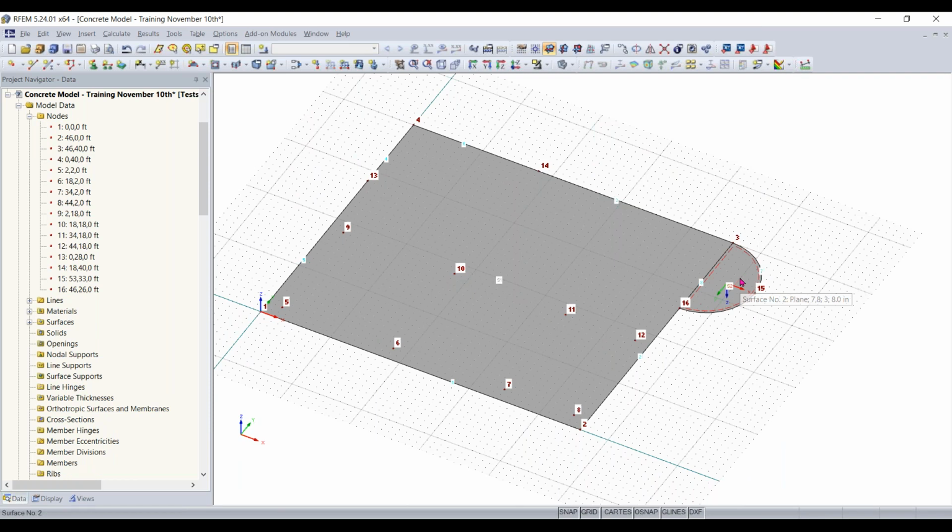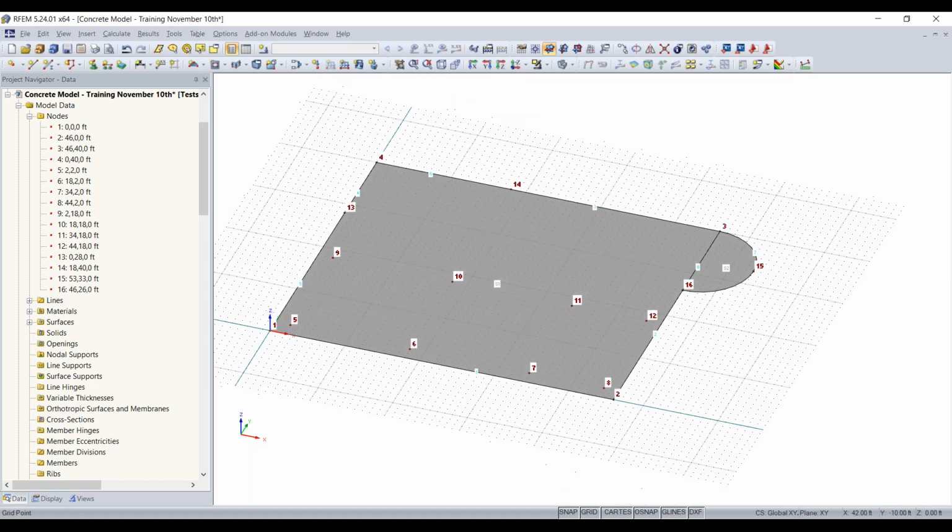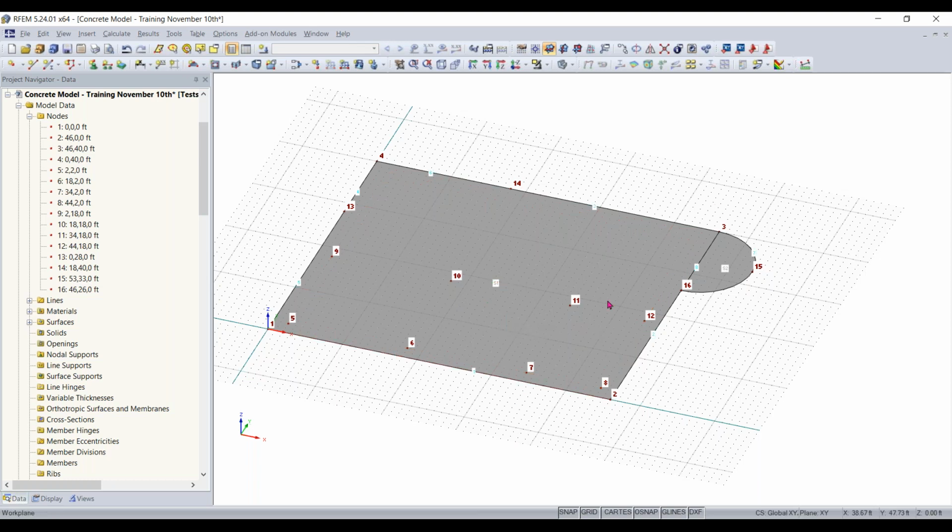And now we can create our ceiling slab. And this is pretty easy because our ceiling slab is identical to our floor slab almost. So the height between our ceiling slab and our floor slab is 11 feet between both of the slabs, but the center axes of the surfaces must have a spacing of 11.83 feet because our slabs have a thickness to them, which is 8 inches. So we want to make sure that the actual spacing between these two slabs is 11 feet, including the thickness of the surface.